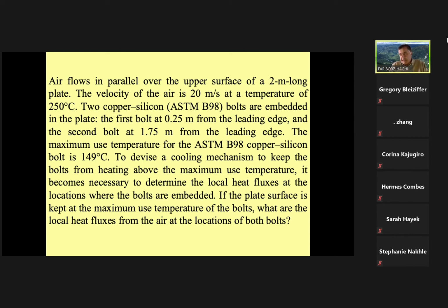Therefore, I can say maximum 149. Now I need the heat flux, therefore I need to calculate the h, my heat transfer coefficient, but I need it at a specific point. Therefore, I need to calculate my h_x at this point.